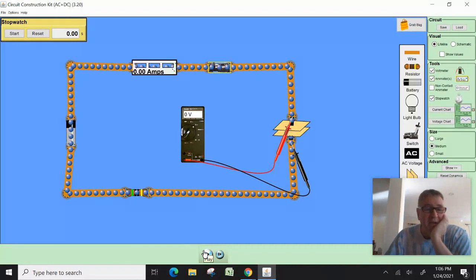I'm going to run the simulation with the switch closed, and then I'm going to stop the simulation and see what our meter readings are, and that will be immediately after closing. And then I'm going to run it for 50 seconds, which will produce steady state. So the two columns on your lab immediately after closing the switch is analogous to me running a program for a trillionth of a second, and then after 5 RC, steady state will be when this thing reads 50.